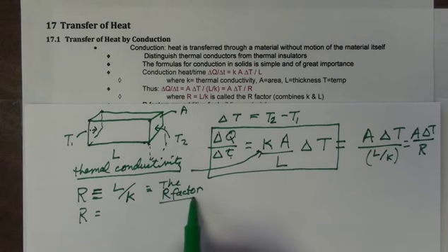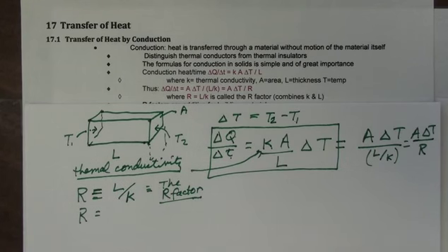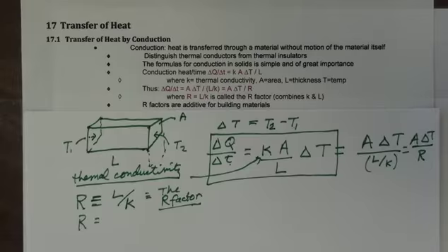And you find out about the R factor when you're using insulation in a home or you're doing any type of insulation. You're interested in this combination of things. What is the length, in other words, the thickness, if you wish, of the substance, divided by its conductivity. And you want a high R value if you want to insulate things. We're going to talk about that in just a moment. But the great thing about this is the R factors are additive. R factors are additive for building materials.